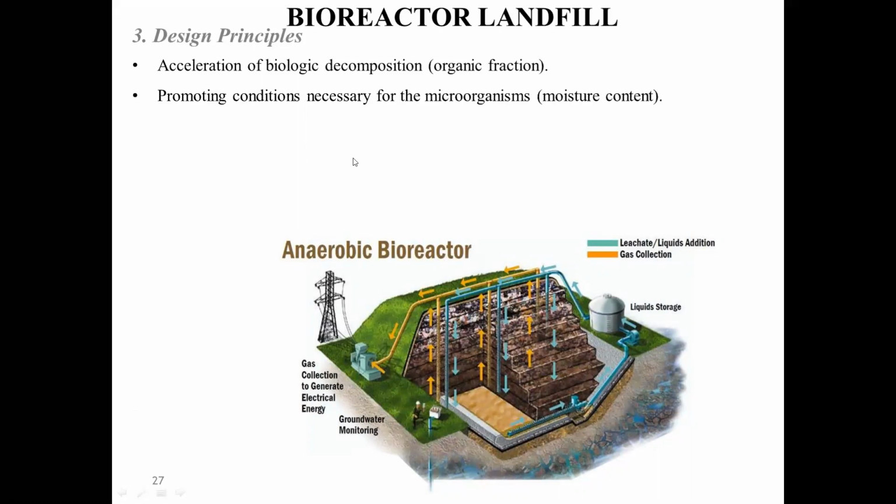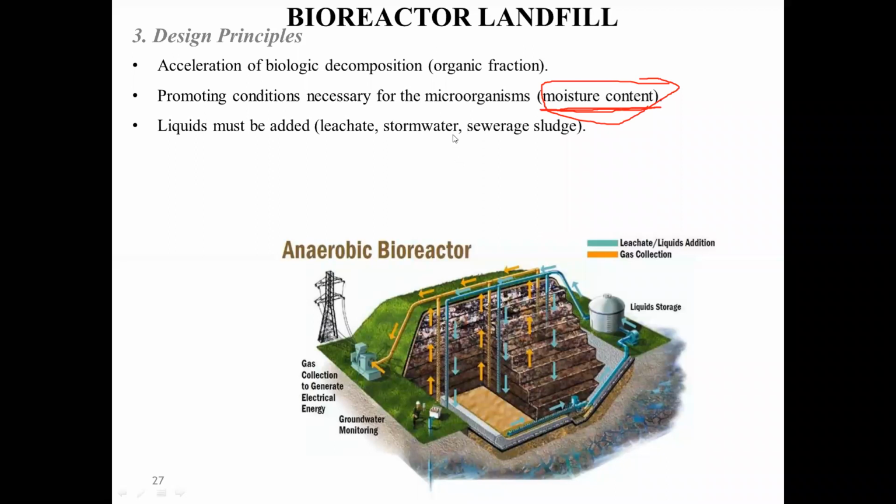Then we are going to be promoting the conditions necessary for microorganisms by conveying water into the waste. By applying the moisture content, the microorganisms are going to be more activated, and the process is going to be faster. So we are going to be adding liquids such as leachate, stormwater, or sludges.